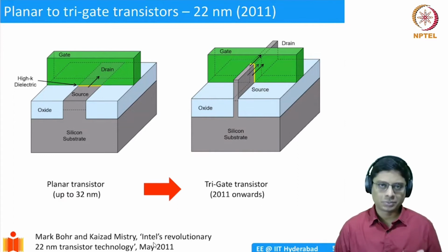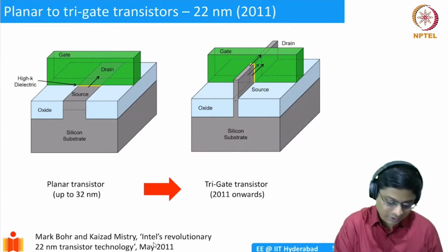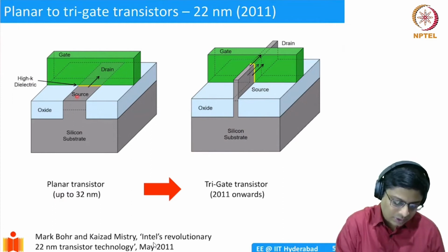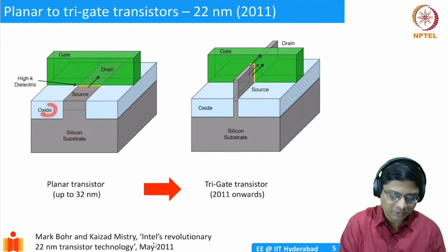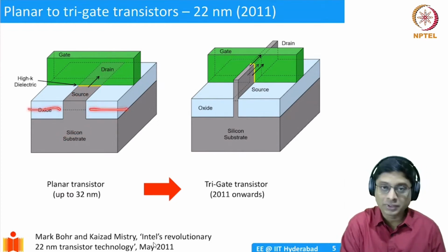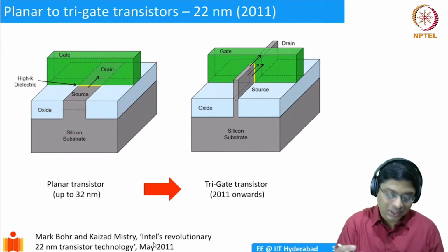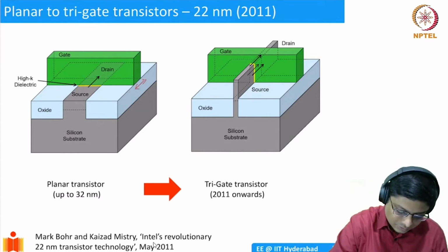The reason they're called planar transistors is that we are familiar with the structure of a transistor. It's just rotated. So basically, you have the source, you have the drain, and you have the substrate. And this is the field oxide that we talked about, or shallow trench isolation, whatever it is. It is the isolation between two transistors. So where is your channel length? Channel length is here. This is the length of the channel, and this is the width of the transistor.